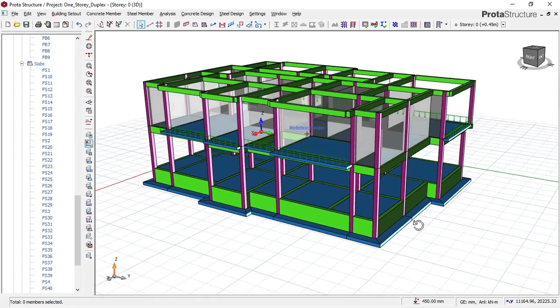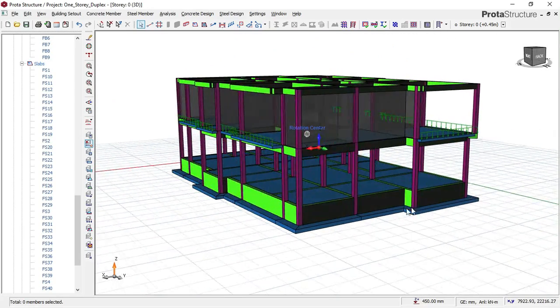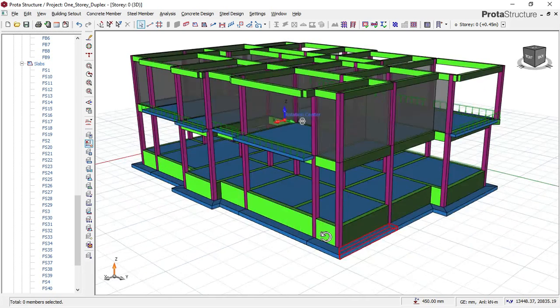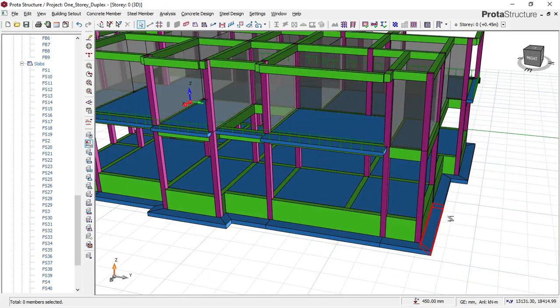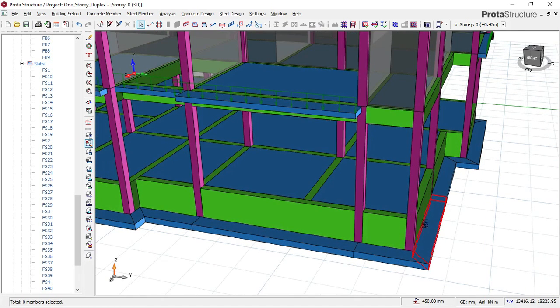Now, when the soil is coming back to its normal shape, it will affect the structure at the bottom, causing it to have an effect of active pressure. Now, if you don't provide this toe on this place, what happens is that the soil tends to pull this structure at the bottom, and there will be an overturn of this beam.